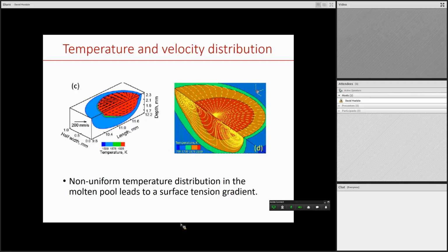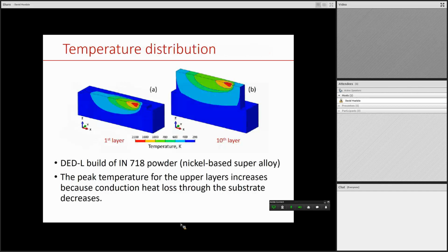I have the temperature profile of a part that's being printed. I sort of have the idea that as the height increases, the temperature profile is going to change. It's going to almost expand. How can I use that to print a better part? Like what controls can I change on an actual additive manufacturing process? Probably the laser power and the scan speed. Laser power and scan speed, yes.